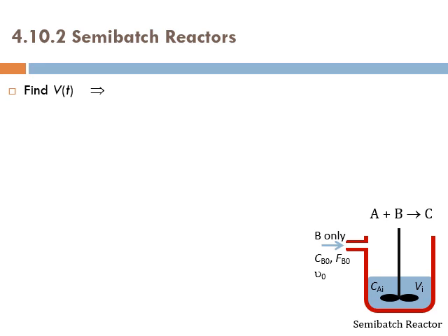So input of the mass minus output of the mass, right, equals accumulation of mass, dm by dt. Which mass? The mass inside the system. That's the mass inside the reactor. Do you have mass leaving the system? No, we don't. We don't have mass leaving the system, so that goes to 0.